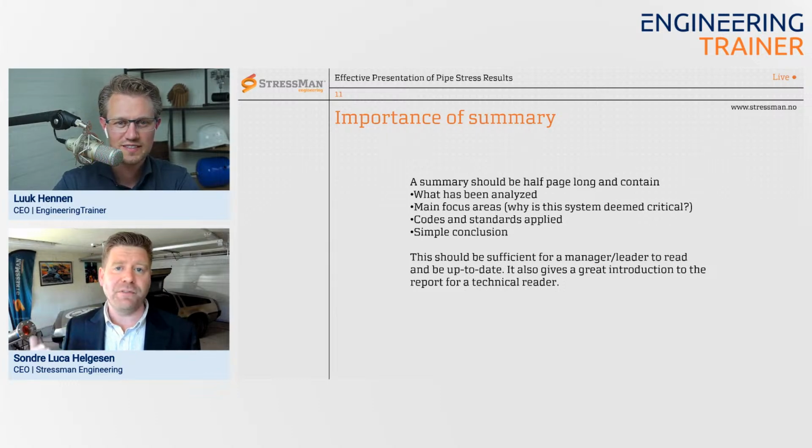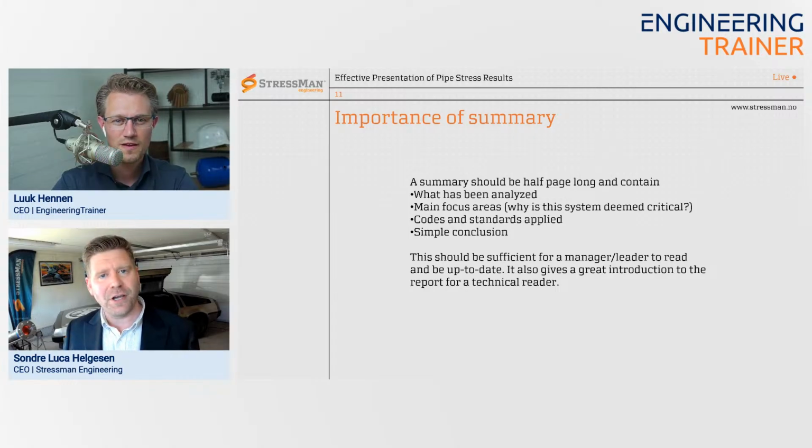But there is one challenge we face a lot here in Norway when we have DNV, and back to that DNV RPD 101, it states explicitly that you have to make your stress isometrics based on the software that had built the model originally. So, for example, exporting from Caesar 2 would disqualify you in this case, which means that if you're only doing the stress, let's say, as in Stressman, we are getting isometrics from our clients, then we will need them to actually make us the isometrics.